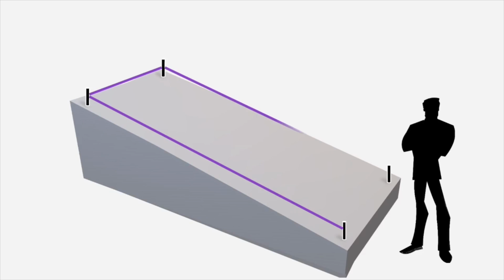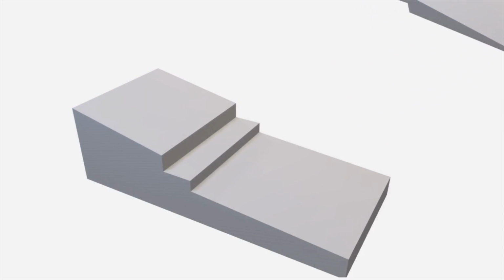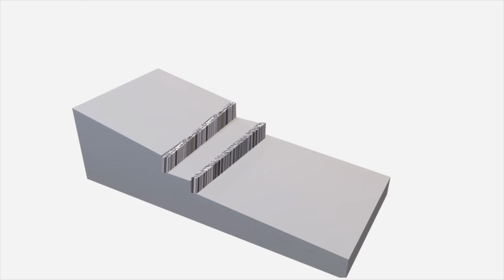Next is the most important part of the process, earthworks. Since the site has a steep slope, minimal site clearing is needed to protect mature vegetation for slope stability. Excavation will then be done to form a level plain, through cut and fill. Then, the surrounding soil will be retained with retaining walls to support the wall and prevent it from tilting from pressure from the earth behind it.